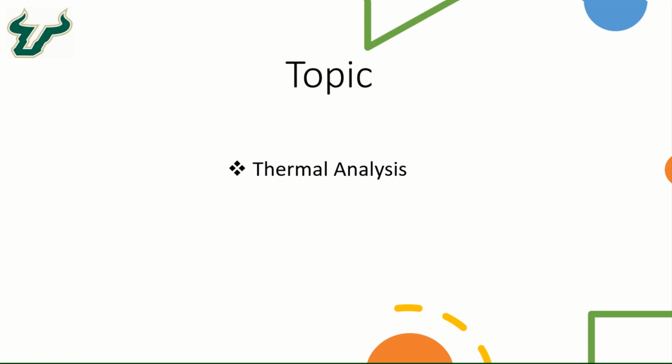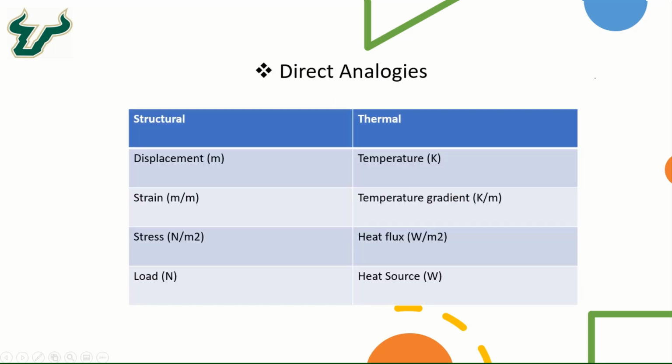The topic is thermal analysis, and specifically we are going to be looking at how to set up the thermal analysis simulations using SolidWorks for a bimetallic strip problem. Okay, so to begin with, let's take a look at the direct analogies between the structural simulation and the thermal simulation and what the similarities are between the two.